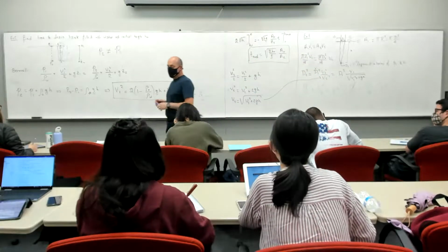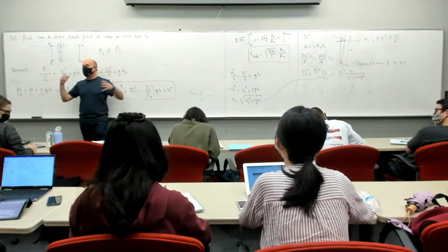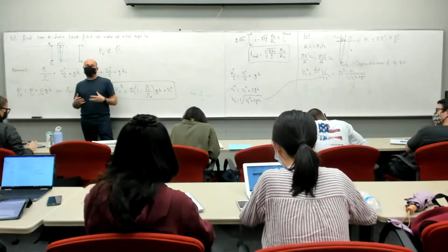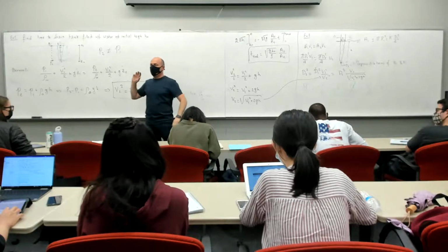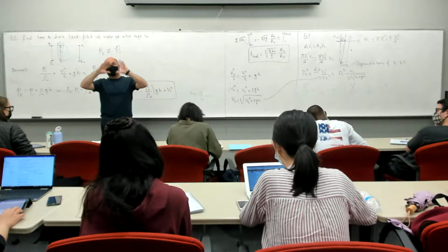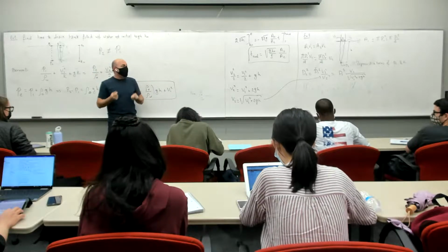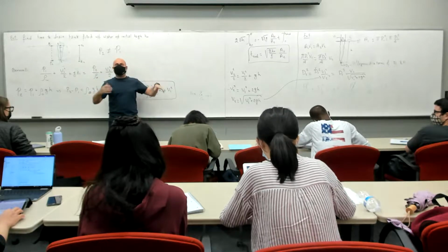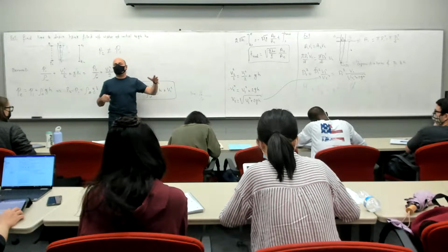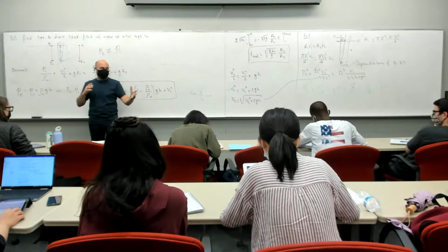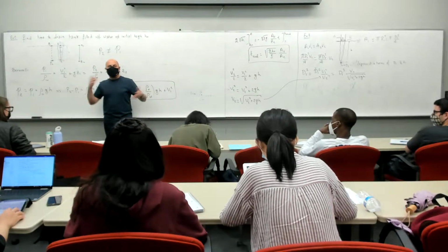Our next step, on Wednesday, we're going to start deriving the full equations. We're going to add the viscous stress tensor. We'll spend some time talking about the viscous stress tensor, what its structure looks like, without really digging into what the values are. We'll expand it, put it in the equation, and derive the equation using the Reynolds transport theorem, doing a shell balance, doing different interpretations for the stress tensor, whether it's a force or a diffusion tensor. We'll know what the tau ij means, etc.